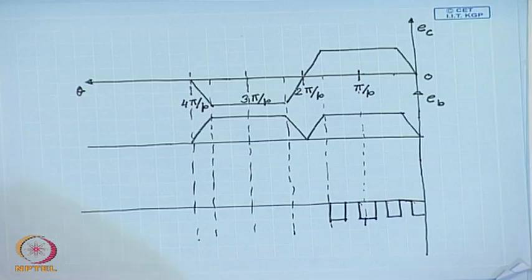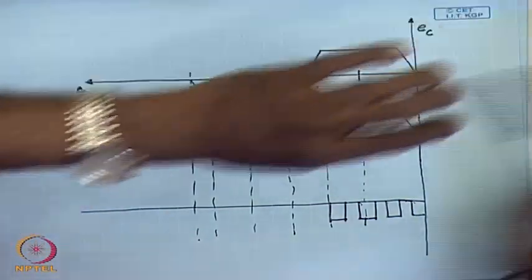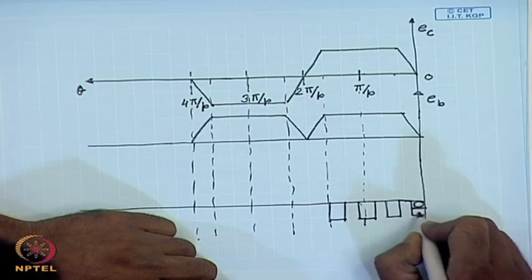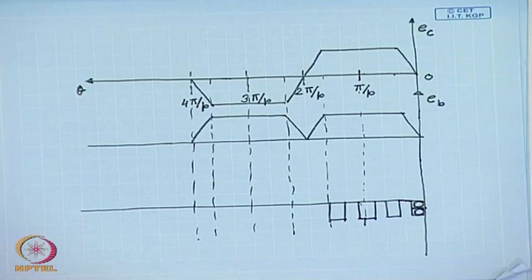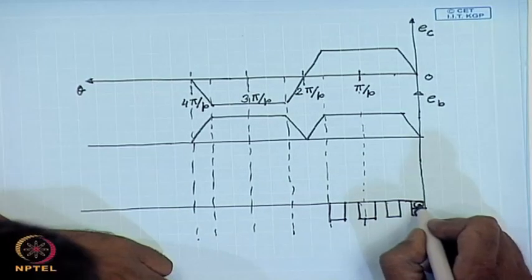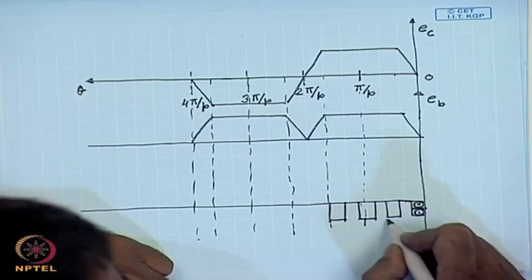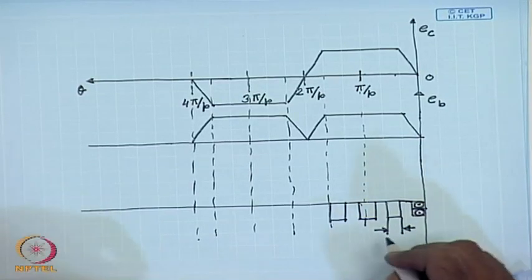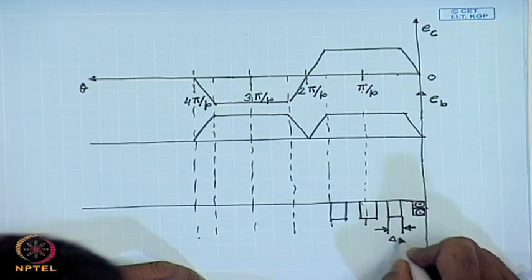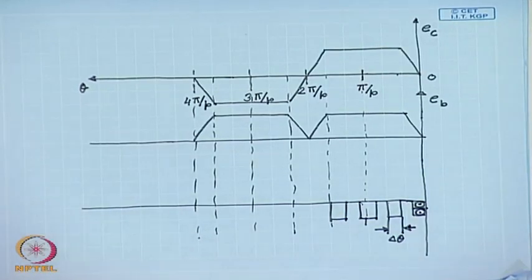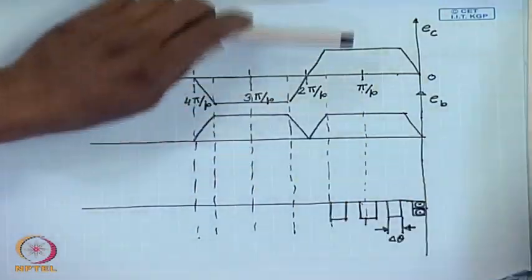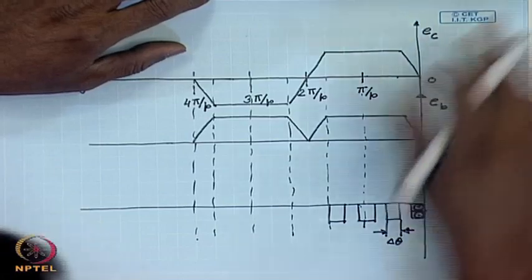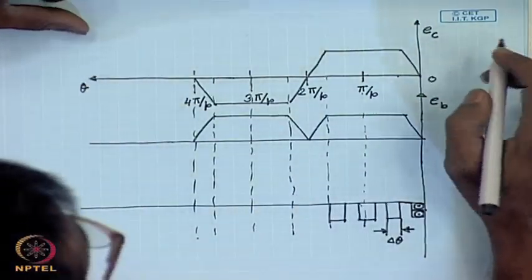And DC machines usually have double layer. So, in each slot there will be 2 coil ends. And if we denote the width of the slot by delta theta, then the number of turns N C in a coil can be represented in terms of delta theta as follows.